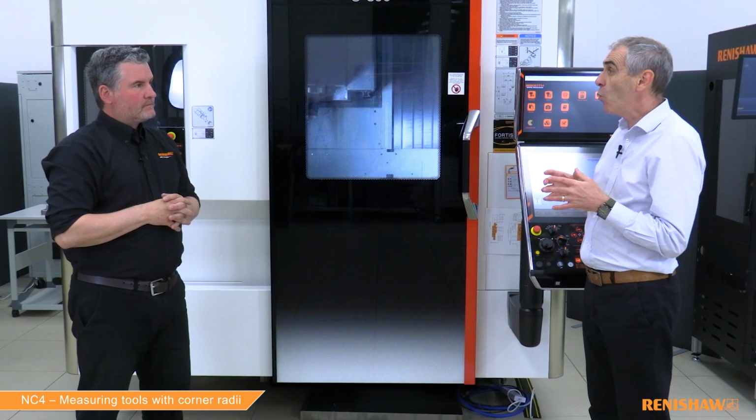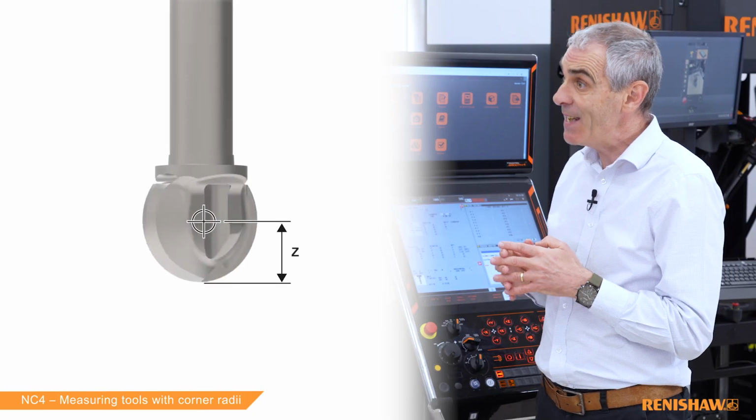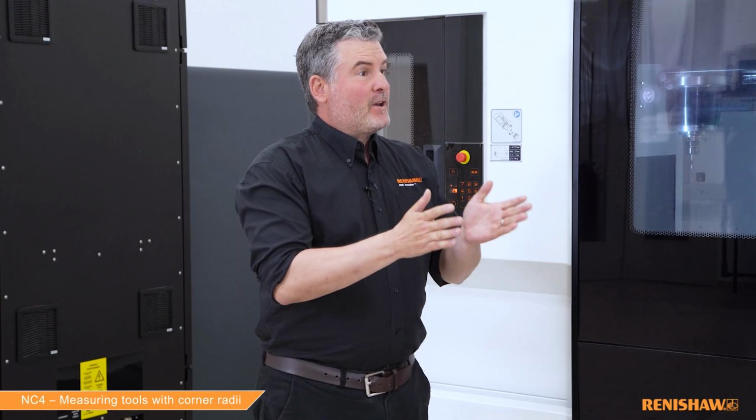So is there anything else our viewers need to consider when using the B1 input? Two things come to mind. Be mindful of the F input, as that dictates how many measured points we'll make on the arc. Unless you're looking to measure the full arc in many places, typically F1, F2 or F3 are the correct number of inputs to use. And secondly, if you're measuring a tool where the ball is almost full form, like a button tool, you must enter the Z input, and that ensures that the initial diameter measurement takes place at the equator of the button. Okay, thanks for that, Ian.